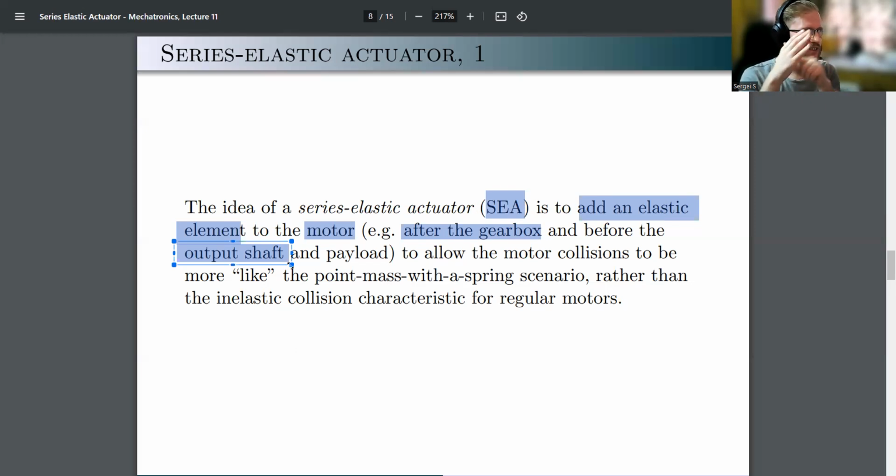What we are doing here is essentially like a motor shaft that rotates like this. And what we are saying is that at the end, there will be a torsional spring. Torsional spring means the spring that can wind up in the rotational direction, and the more it rotates, the more torque it outputs. Deformation of the spring is rotational, not linear extension, but rotational wind up.